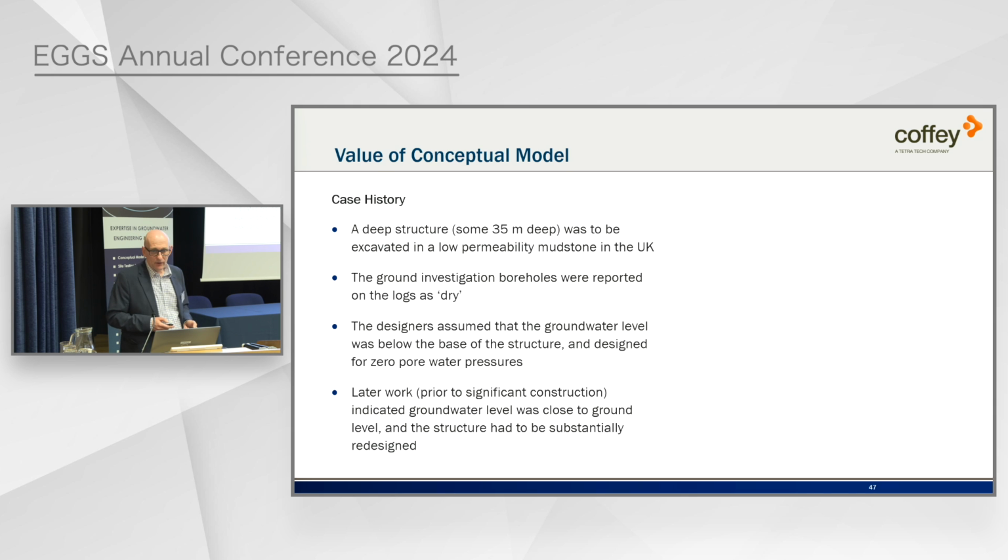I've got a case history here that I was involved in a review capacity. It's a structure somewhere in the UK in a local mudstone, and the groundwater from boreholes, without exception, reported the logs as dry. No surprise there, we're in mudstone. And it pains me to say, but the designers, not a company I personally work for, assumed that the ground level was below the base of the structure, and furthermore, they designed for 0 pore pressures. Luckily, before construction started significantly, someone reviewed it, and they discovered that the groundwater level was actually close to ground level, and the structure had to be significantly redesigned at quite a lot of inconvenience.